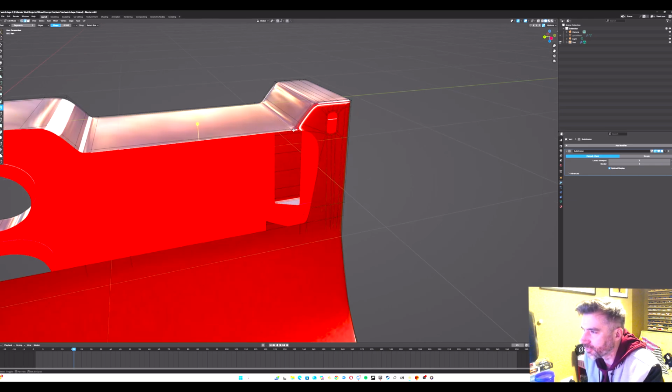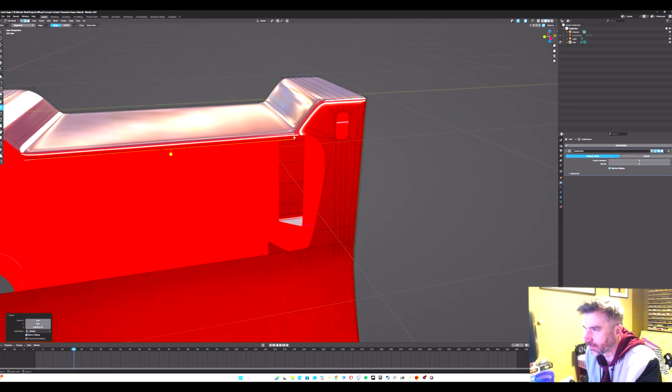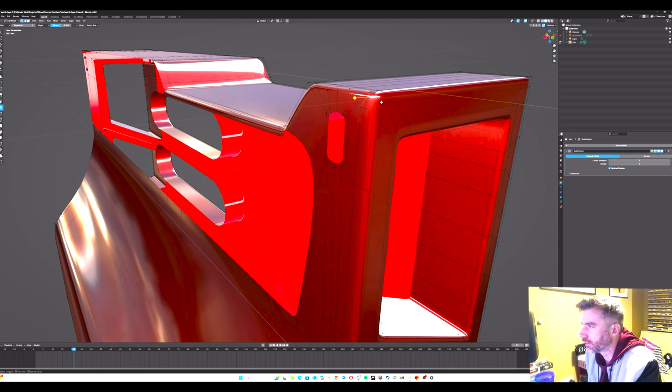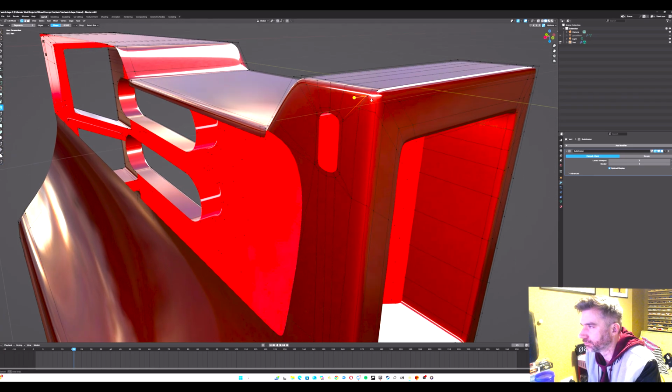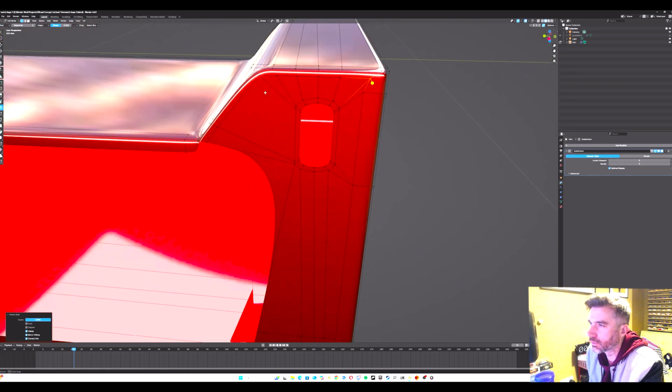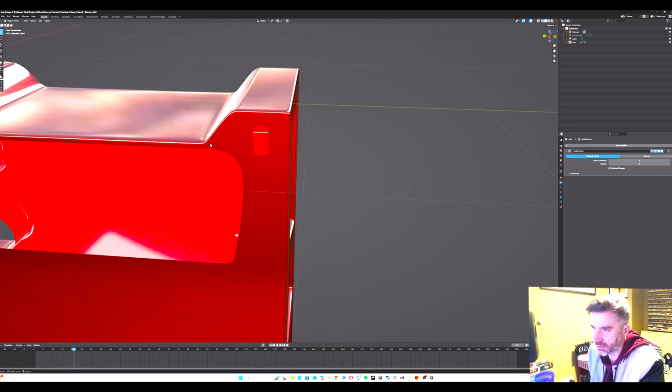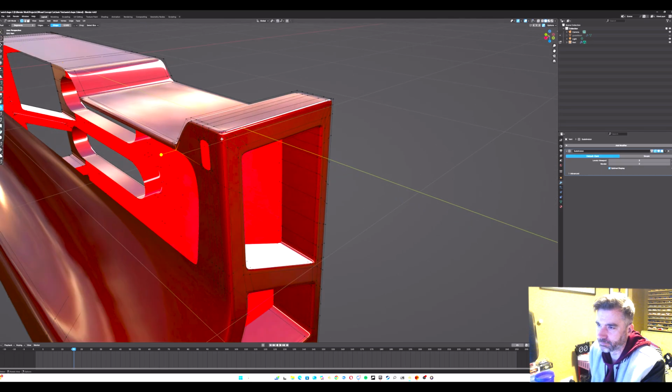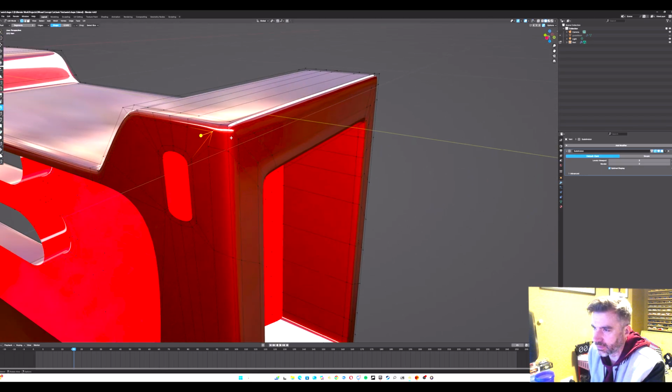Okay, so let's do some of these jobs the way we could maybe have done them before. So we can extrude this down, and then I can cut a new edge along here to tighten this up, and then that can connect to here in a minute. And then if we join these 4, 3 even, and then slide that down, so we've got a tighter edge there. And the only thing that needs fixing here is these 2 need to connect something else, so I'm going to subdivide this.